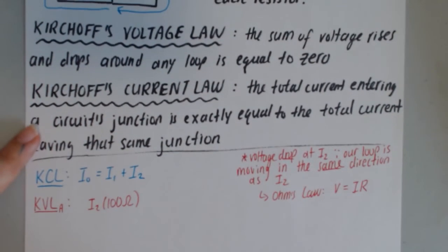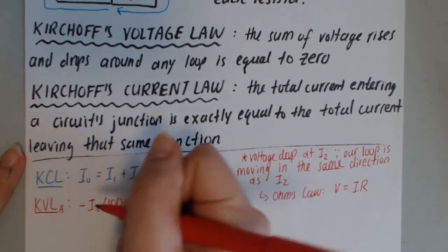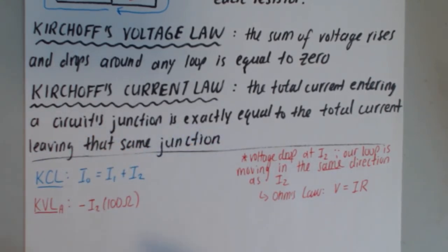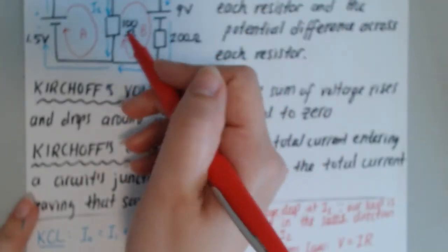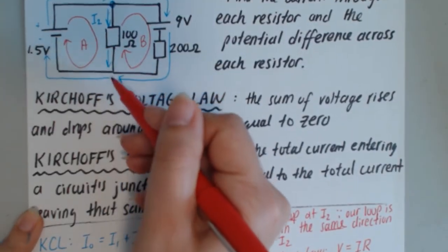That's my first voltage drop. And since it's a drop, I'm going to stick a minus sign in front of it. But this whole thing is voltage, right? Don't forget, this is a voltage drop, minus V1, you could call it if you want. Okay, next, now we keep following the loop to see what else is happening.